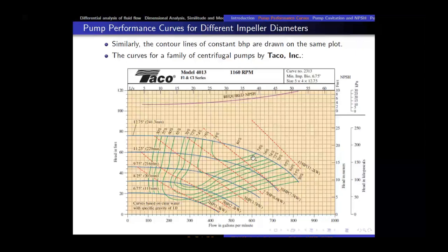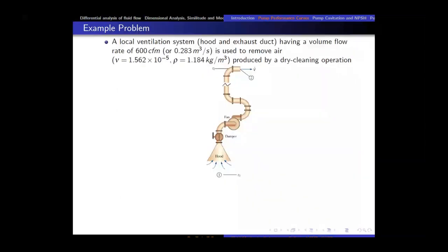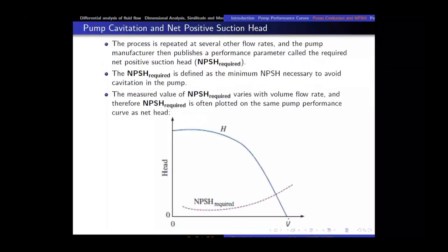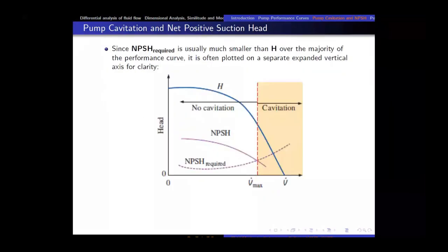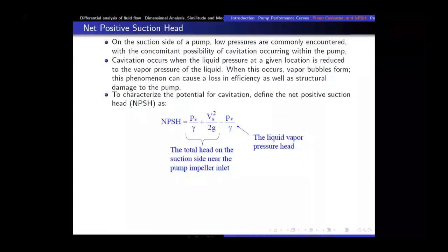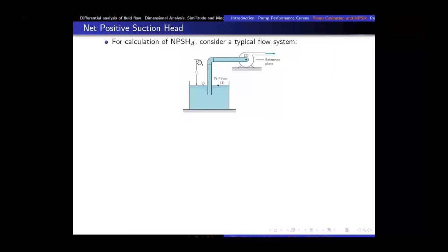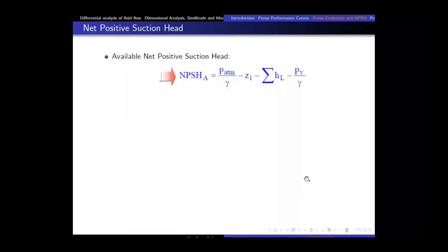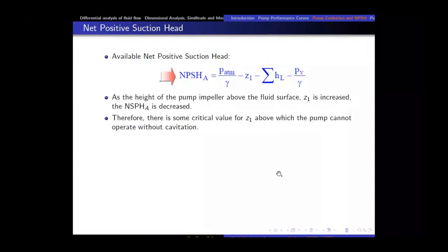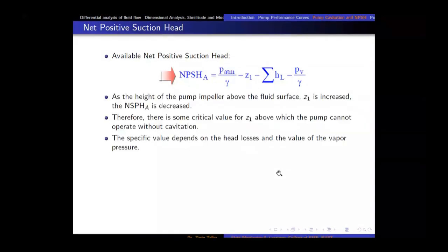to avoid cavitation. To avoid cavitation, the rule of thumb is that the elevation difference between the pump and the storage tank should be very small, and if the storage tank is on the upper side, then cavitation would be practically impossible. Because in that case, the elevation head would be added rather than subtracted, right? So I hope that this point is clear.